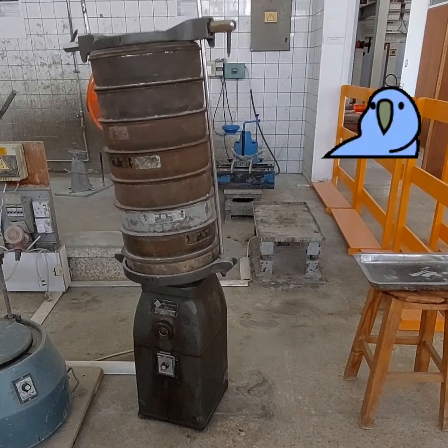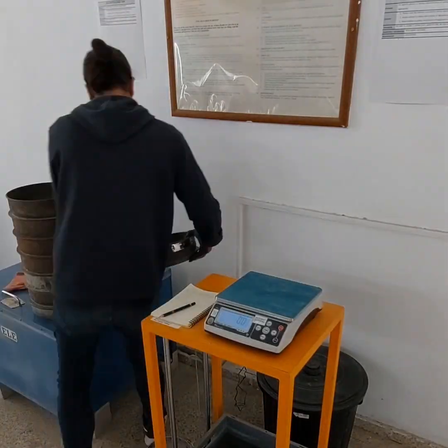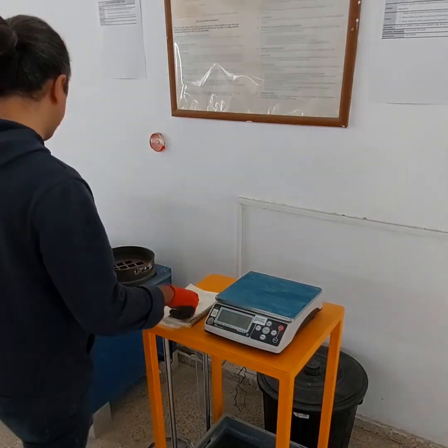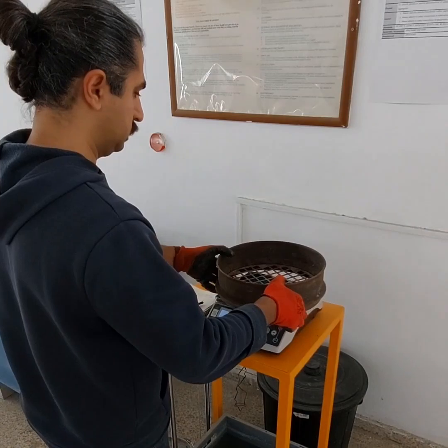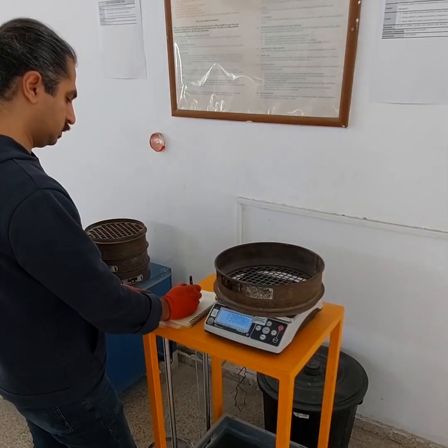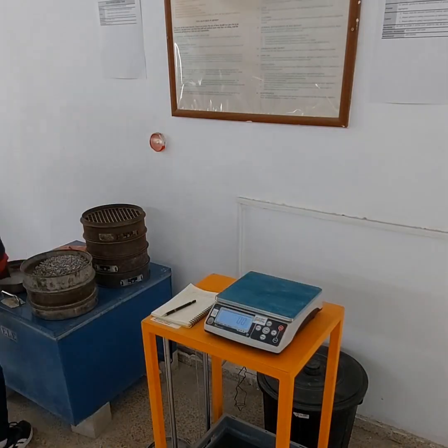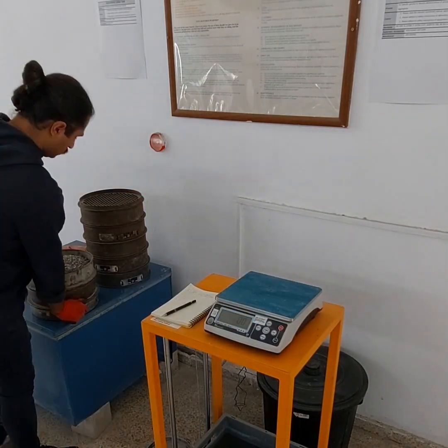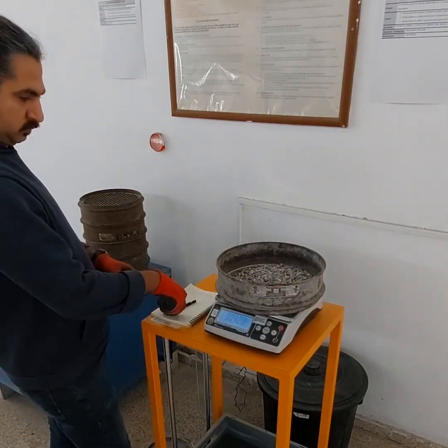After shaking, I determined the mass of each sieve with the aggregates. Then I subtracted the initial weight of each sieve from the value that I obtained and found the weight of aggregate retained on each sieve. We should add all the aggregate weights together and compare the total mass of the material to the original dry sample mass placed on the sieves. If the amounts differ by more than 0.3%, we can't use the results and we should repeat the test.